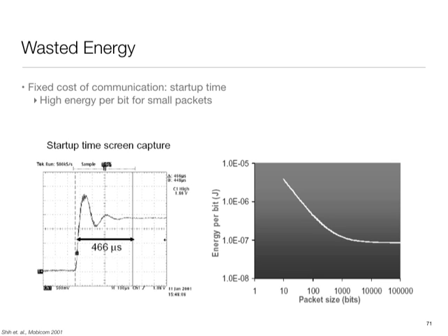So if you think in terms of energy per bit, the model I had was ignoring all this stuff because that energy per bit was energy per any bit, not energy per truly useful application bit. So that overhead somehow also needs to be factored in and honestly accounted for. By the time you look at the energy per bit number for the true application relevant information bit going out, it's going to be a lot higher, particularly in this domain of short range radio applications which send a little bit of data. So we don't have opportunities for packing lots of data. So these are issues one has to keep in mind.